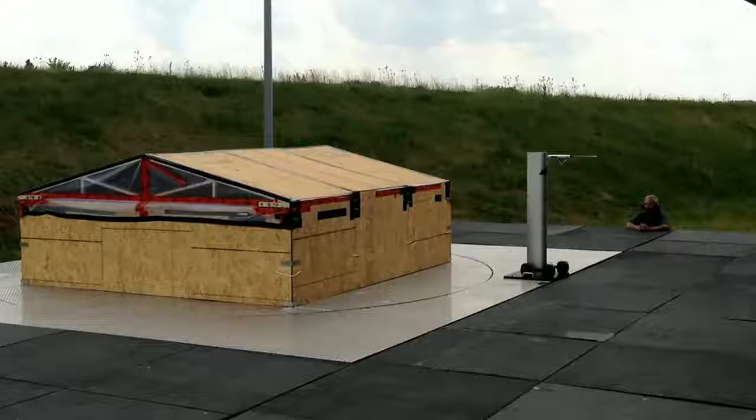Finally, failure culminates with all roof-to-wall connections fully withdrawn from the top plate, at which the roof is overturned about the leeward wall. In this test, however, overturning is prevented with the use of internal cabling to protect the surrounding testing environment.